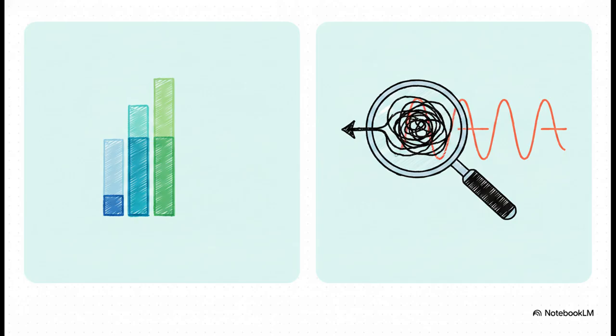is actually distributed. We generally have 2 main ways to calculate this power spectral density, or PSD. The first method is the periodogram. Mathematically, this takes a time-windowed signal, calculates its Fourier transform, and then computes 1 over N times the magnitude of that transform squared. The catch here is that this result is random for each realization, so it requires a lot of averaging. The second method is the correlogram.